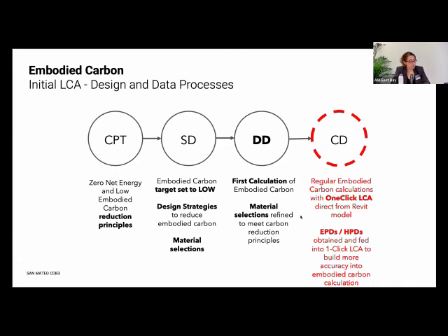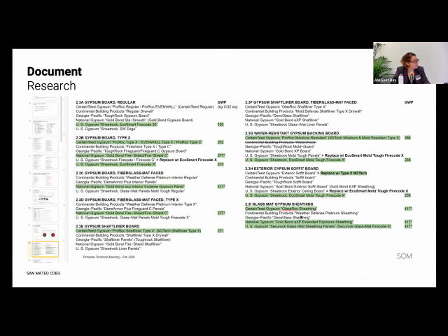So in looking at this for the CDs, the contracting team can't read our minds. We have to write this down. So again, here's some of the research we had in gypsum board. We actually wrote the global warming potential limits into our specifications. And so do remember all the points that Emmy had mentioned and what she was looking for from her side, from the construction side.